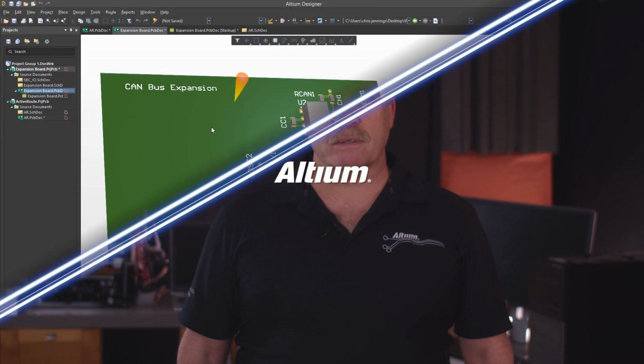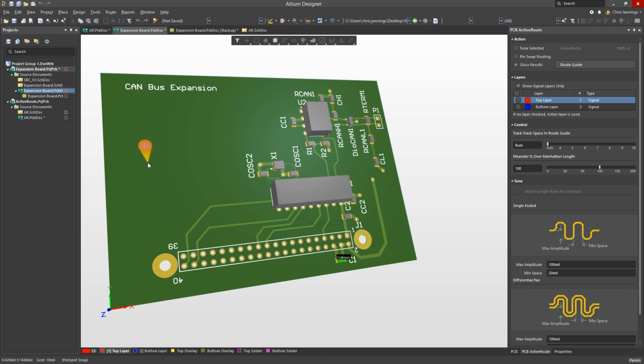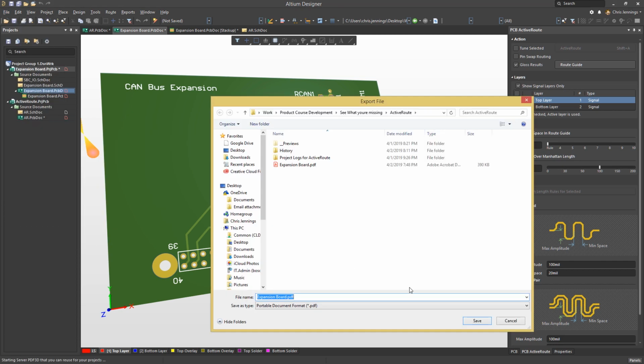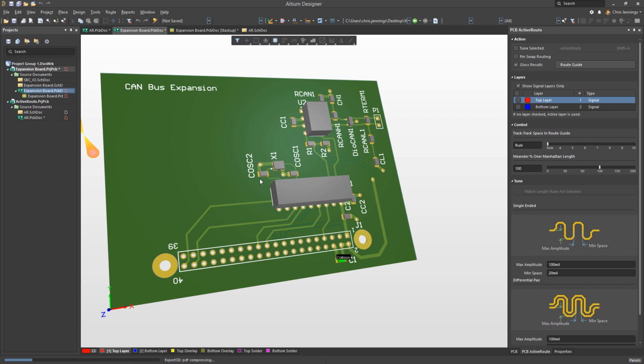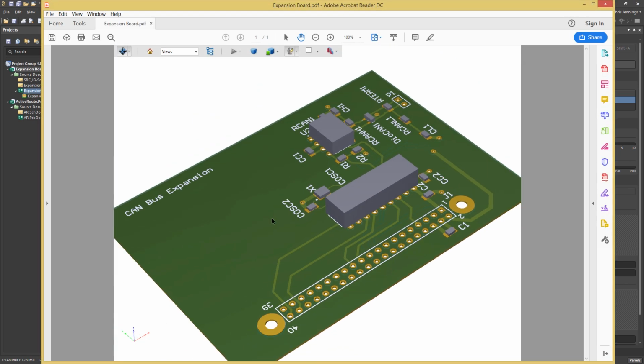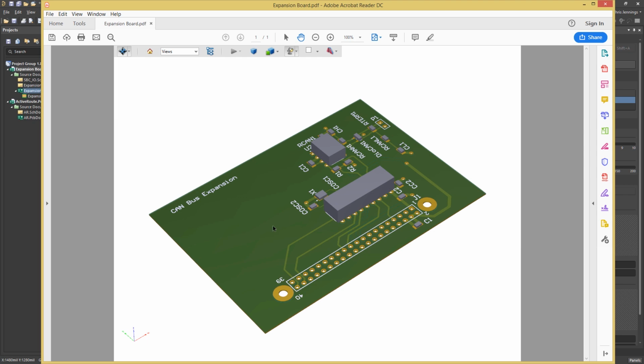The PCB can be viewed in both 2D and 3D. A new feature is the ability to export a 3D PDF file. This file is a portable 3D view of the board, and along with Draftsman documents, can be very handy for documentation. To output a 3D PDF from the PCB view, click on the File pull-down menu, select Export, then 3D PDF. I normally leave the defaults. This generates the PDF file and opens it. You can manipulate the board in 3D, rotating, zooming, etc.